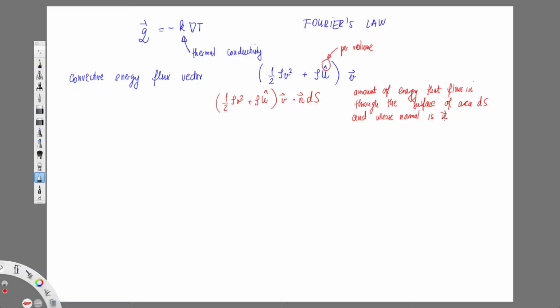So that's how divergence is related to integrals over the surface. All right, and is this all? What else might happen? There's friction working within my volume. Even if I just flow in, there are still some layers that are moving at different velocities, okay? And that is doing work on my fluid element and might heat it up.